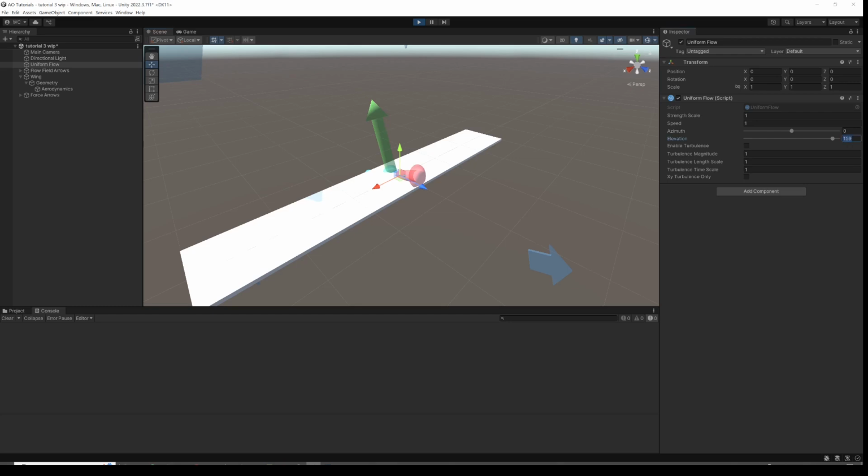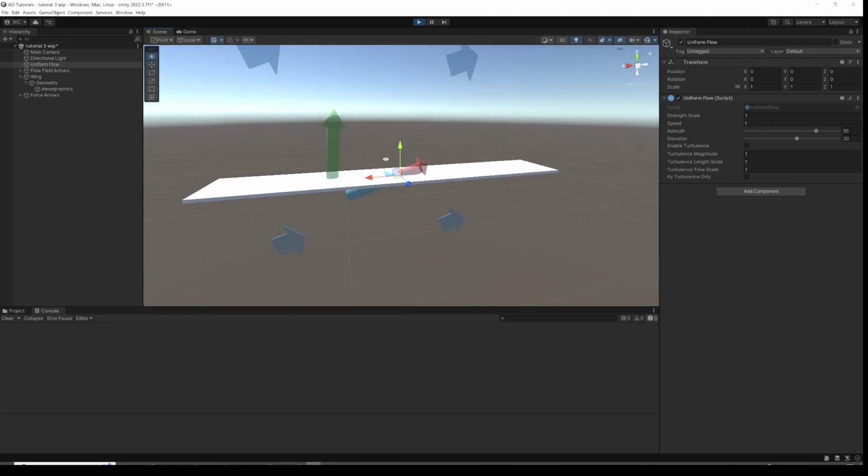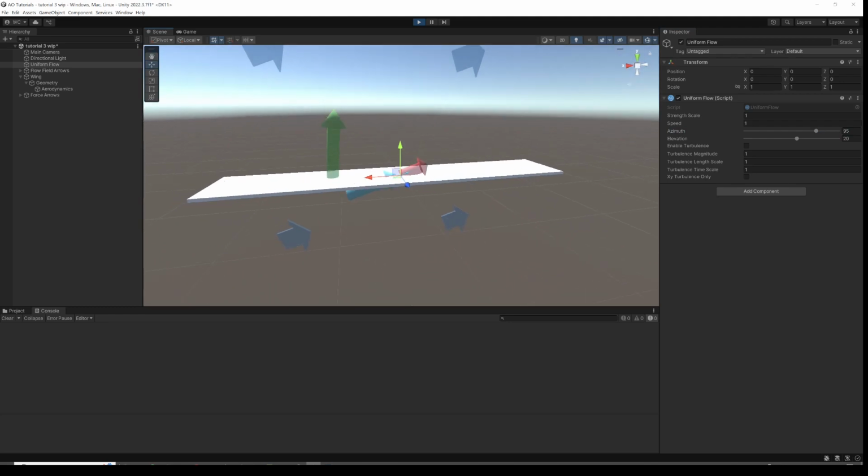One other thing we can look at is what happens to that aerodynamic centre when we have a side slip or azimuth. So if I vary this, we can see as we get round to our flying sideways, that aerodynamic centre has moved out to there. So it's now roughly a quarter of the way back, or in the chordwise sense this way. And so that's the correct position. So if that was our flying ruler, you would find in practice the lift on that ruler is acting somewhere around here. So it probably would pitch up. If you launched it in space like this, it would probably pitch upwards.